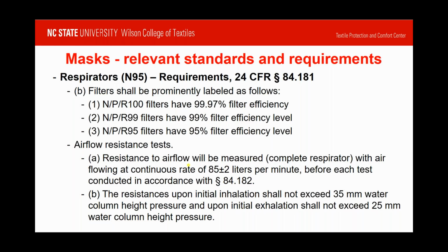There are separate procedures where true human airflow is also simulated, but the essence is 85 liters per minute airflow, and the inhalation and exhalation resistance when that flow is being used shall not exceed 35 millimeters water column pressure or 25 millimeters water column pressure, respectively, which is equivalent to 350 and 250 Pascal.